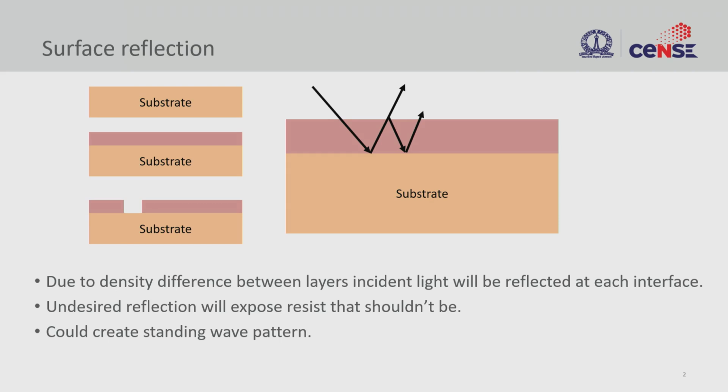So when you take a substrate and coat it with photoresist here, and then you illuminate, and then we create a trench. This is a very simple process, and this is achieved by illuminating it, let's say through a mask. It could be contact mask, or proximity, or this could be projection. So in all three cases, you have a light beam coming onto the photoresist.